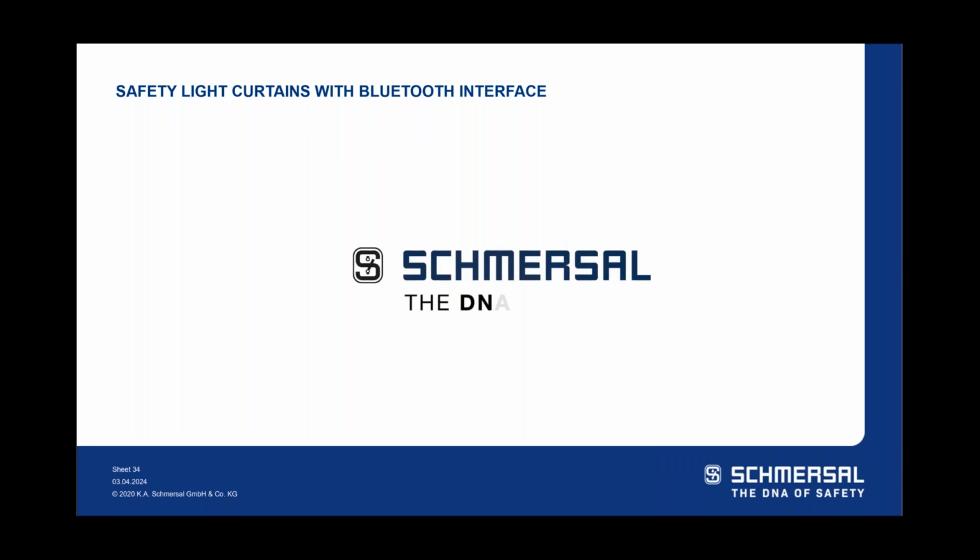Hey, open your app. What are you seeing? What's it saying? What's the error? Let me see all your beams. What's going on? Maybe they're dirty, and you can see on your picture there that some of the beams are grayed out. Like it just needs to be cleaned. Maybe you have no stars when it comes to your alignment. You tell them, hey, just loosen it up a bit, fine adjust those emitter receiver until you get 3 stars, and then you're good to go. So again, too bad about the audio, but that's in a German accent. That's what he was saying.